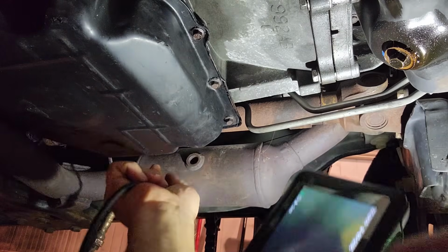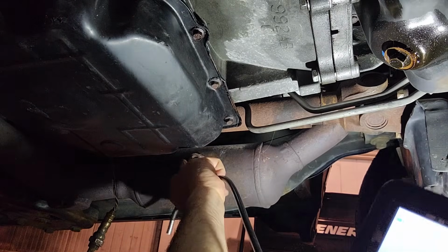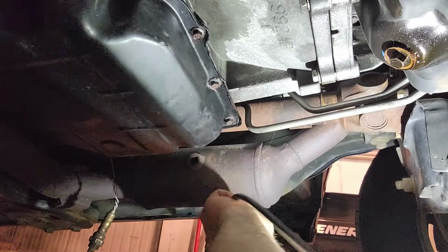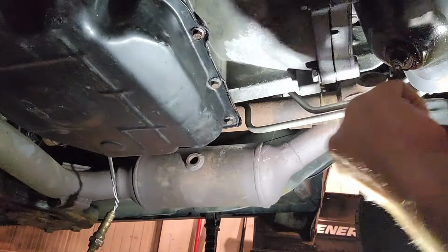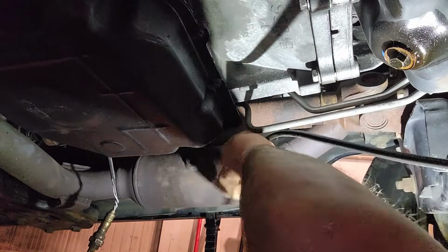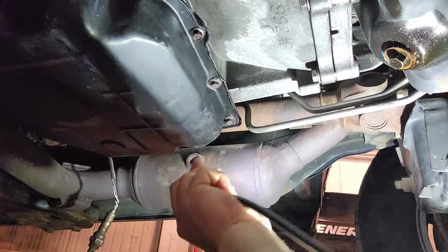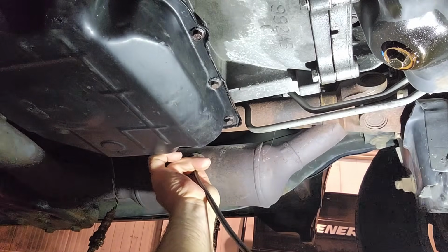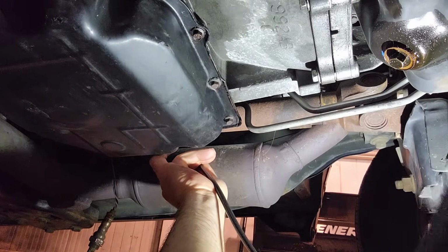If you needed to test it, you could put something right in here, or you could just run it without these in it, or the upstream one if you really want to make sure there's no restriction in here. If it runs better without the upstream in, then you really got to suspect these. Now that's what a diesel one looks like. I know it's not the greatest image, but hopefully it shows up a little bit better when I upload it to the screen.